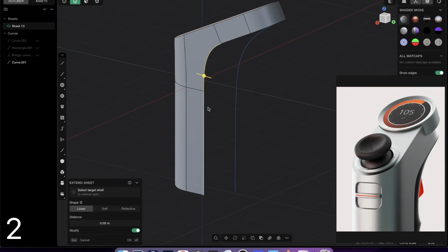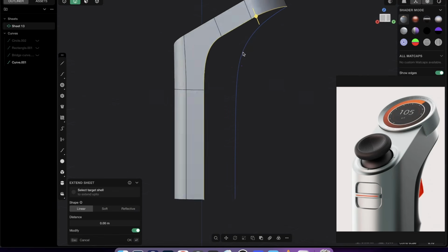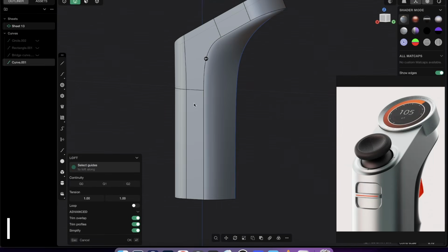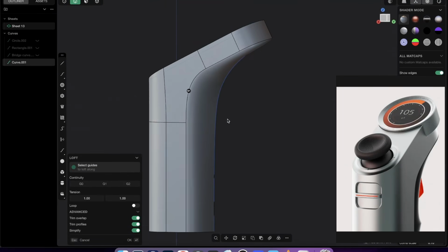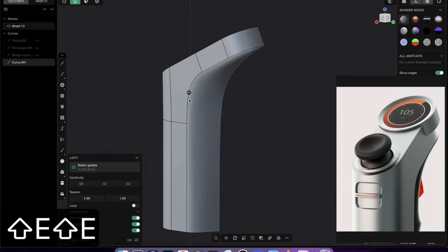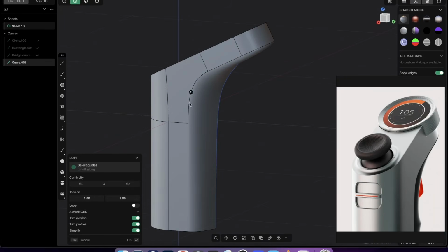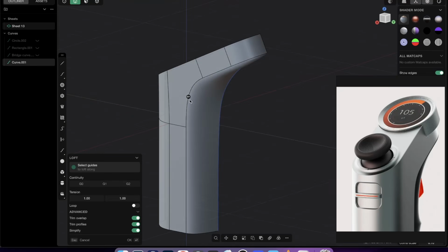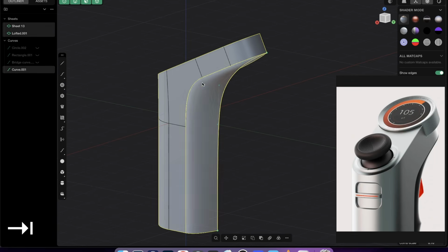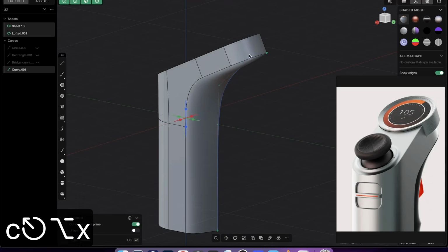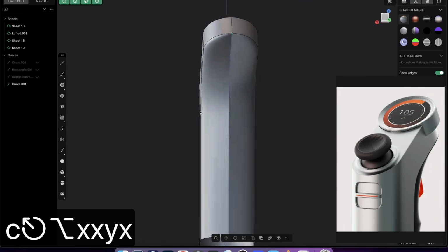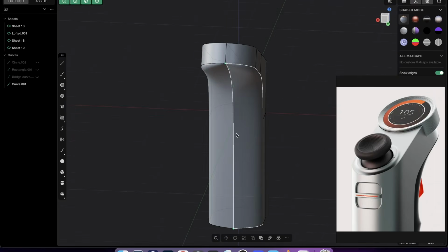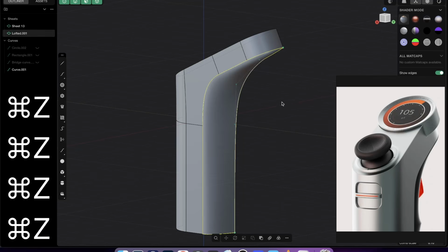So now we can't just select all of those edges here and this curve and loft it, because you see, maybe some beginner would think, oh yeah, okay, that kind of works, but not really, because you see we only have here G1 option and not here the below curve. So if I would accept that, right click and let me just mirror that over. And then you see you have this super sharp, ugly edge here. So Control Z, Control Z.